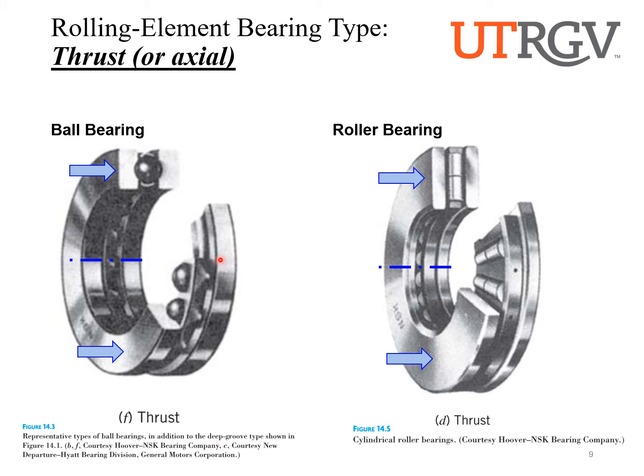So you remember when we did the statics problems, we said, oh, we have journal bearings and we have thrust bearings. So the previous picture for the radial bearing, those are what we typically call the journal bearings in your statics. It means the same thing. They're just taking radial loads. If a bearing has the capability to take the thrust loads, right?